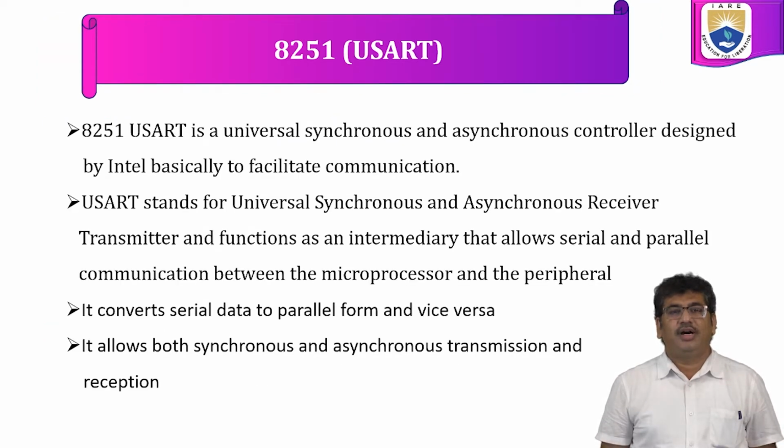8251, which is the USART, is a universal synchronous and asynchronous controller designed by Intel basically to facilitate communication. USART stands for Universal Synchronous and Asynchronous Receiver and Transmitter, and functions as an intermediary that follows serial and parallel communication between the microprocessor and the peripherals.